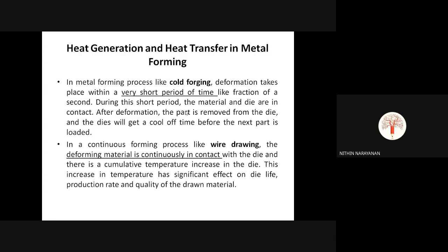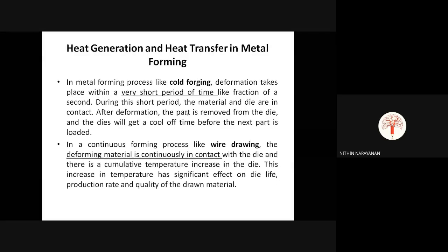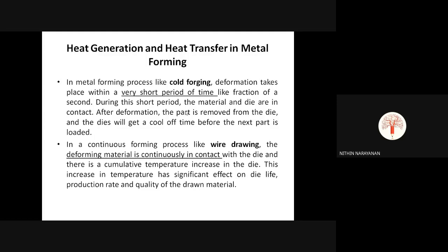Whatever heat is transferred to the die will be cooled off, because after striking one piece, we get some time before striking the next one. So sufficient time will be available for the die to cool off. In the material's case there is no problem either; it also gets the same time to cool off. But in a continuous forming process like wire drawing and all, the deforming material is continuously in contact with the die, and there is a cumulative temperature increase in the die.